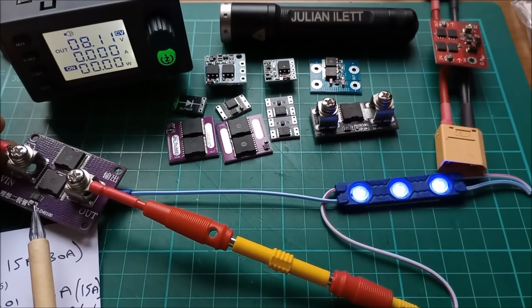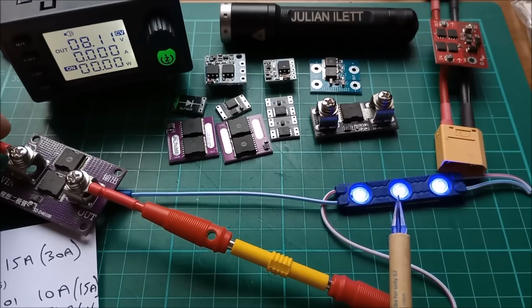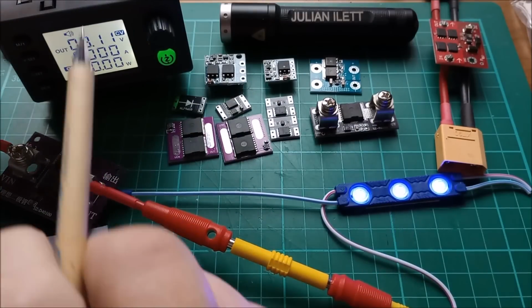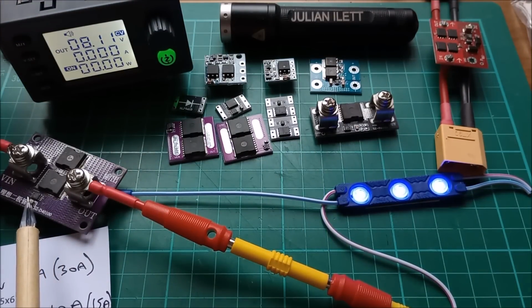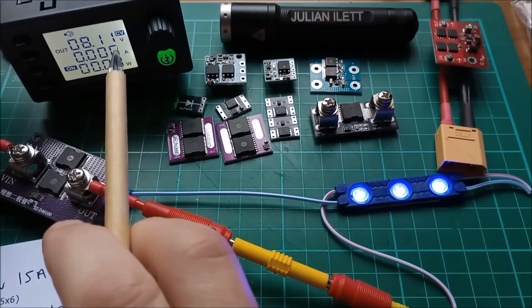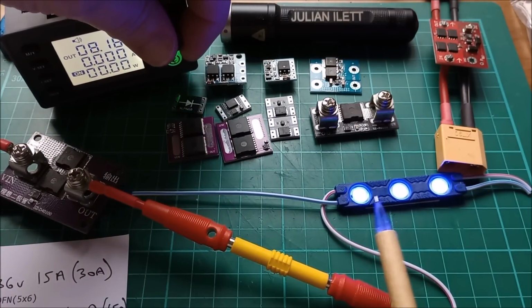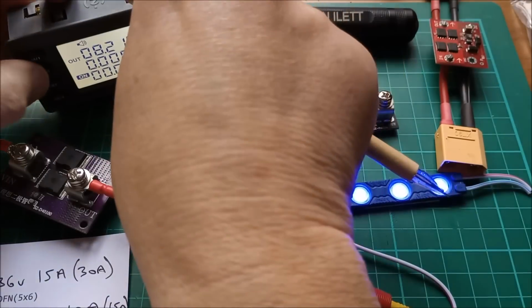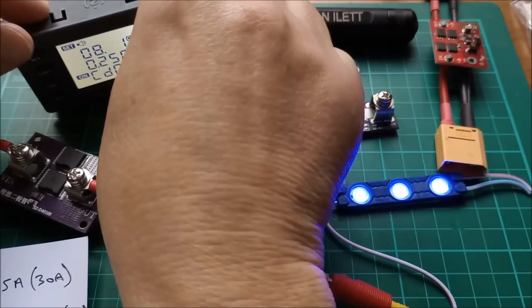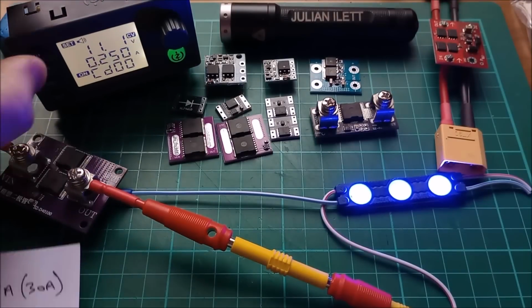74610 ideal diode controller. At the beginning of the video I showed these LEDs going dim for quite a substantial amount of time, and this is a bit of trickery really, because I've just picked a voltage where the ideal diode is barely struggling to work because there's just no current running through it. If I turn this voltage up, it's at 8 volts only because of these 3 diodes in series. So let's go V set, take that up to, I don't know, 12 volts or something like that.